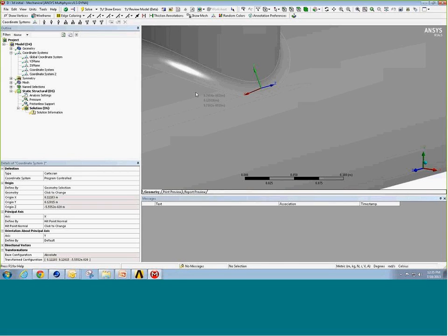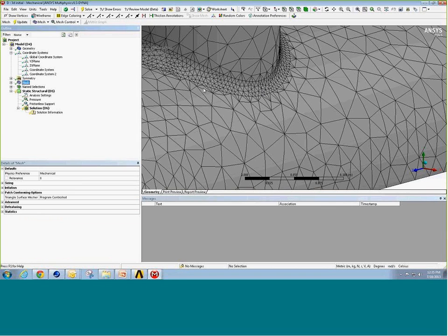Right now, you can't do a corner crack. It has to be a full elliptical crack. I'm sure a lot of these limitations will go away. Okay, so you'll notice that we already have a mesh in our model, so we're going to have to insert the information for our crack and then tell it to remesh this local region.